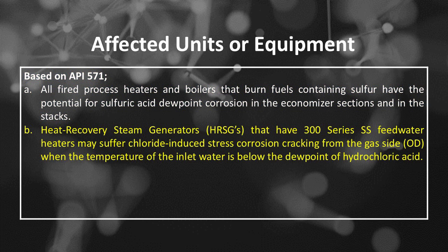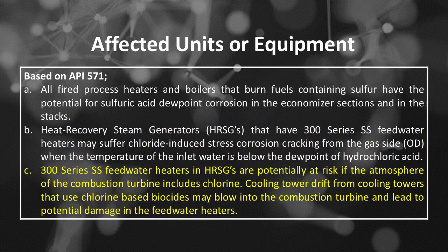Number B. Heat recovery steam generators, HRSGs, that have 300 series SS feedwater heaters may suffer chloride-induced stress corrosion cracking from the gas side, OD, when the temperature of the inlet water is below the dew point of hydrochloric acid. Number C. 300 series SS feedwater heaters in HRSGs are potentially at risk if the atmosphere of the combustion turbine includes chlorine. Cooling tower drift from cooling towers that use chlorine-based biocides may blow into the combustion turbine and lead to potential damage in the feedwater heaters.